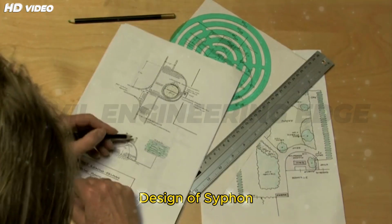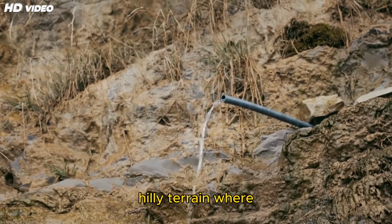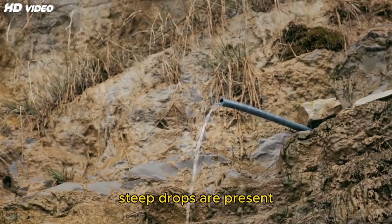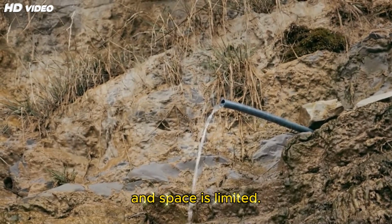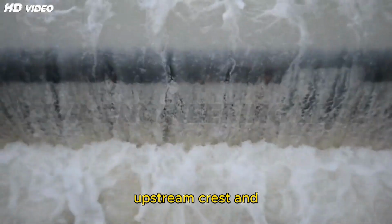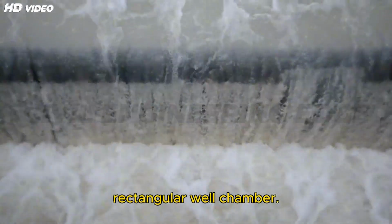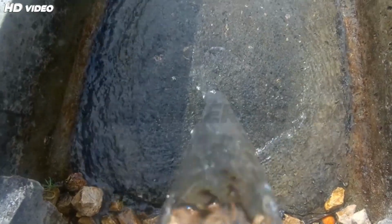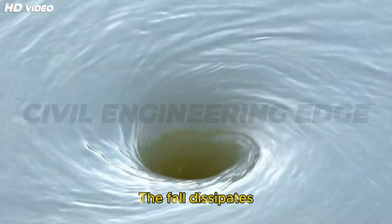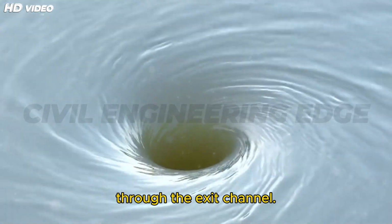Segment 5. Design of Siphon Well Drop. A siphon well drop is used in hilly terrain where steep drops are present and space is limited. Working principle: water flows over an upstream crest and drops vertically into a cylindrical or rectangular well chamber. It then flows out through an outlet channel at the bottom. The fall dissipates energy due to turbulence within the well and through the exit channel.